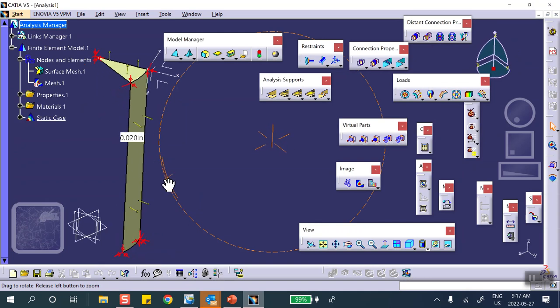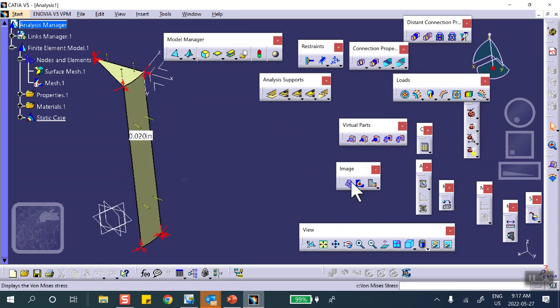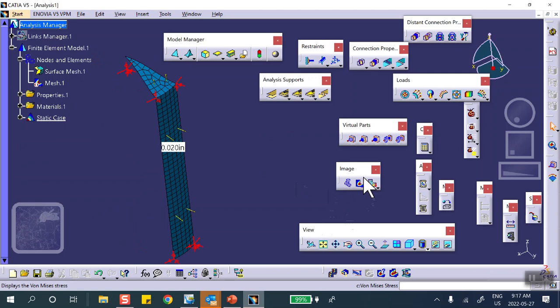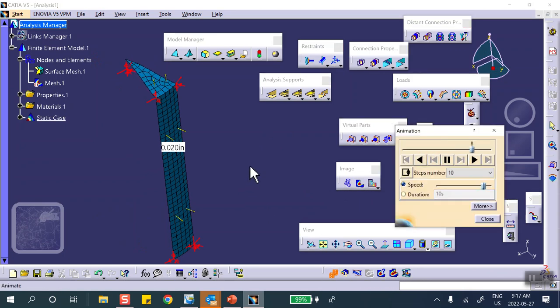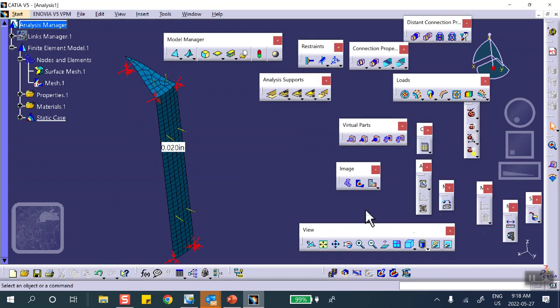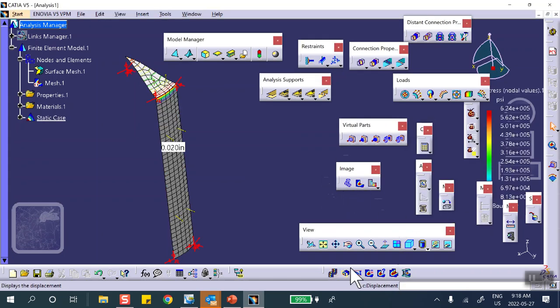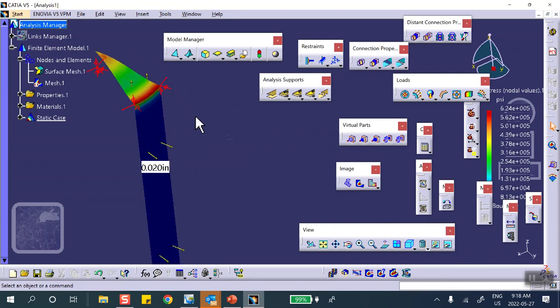Done. Look at the transformation. That doesn't surprise you. Doesn't surprise you because the piece of this entire structure that's most flexible is on the top and the bottom. Trying to expand the periphery is going to be harder. Okay, but these two bulge out. Okay, if you look at the von Mises stress, you're going to do some detailed work here.